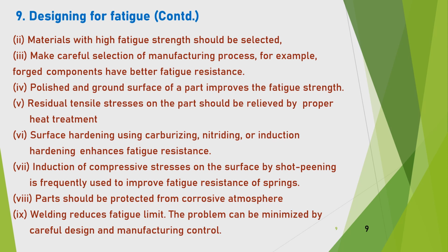Surface hardening using carburizing, nitriding or induction hardening enhances fatigue resistance. Induction of compressive stresses on the surface by shot peening is frequently used to improve fatigue resistance of springs. Parts should be protected from corrosive atmosphere. Welding reduces fatigue limit. The problem can be minimized by careful design and manufacturing control.